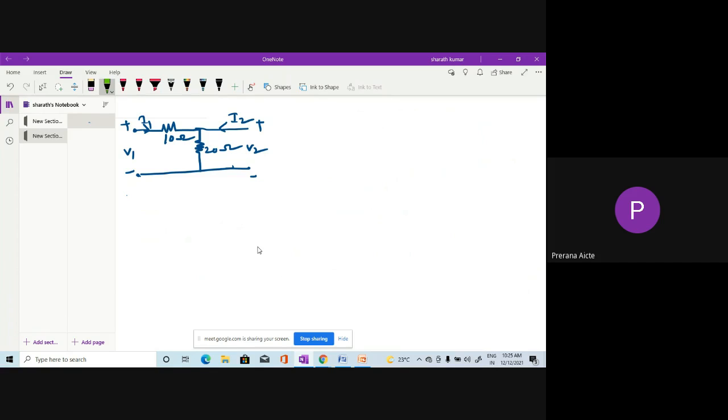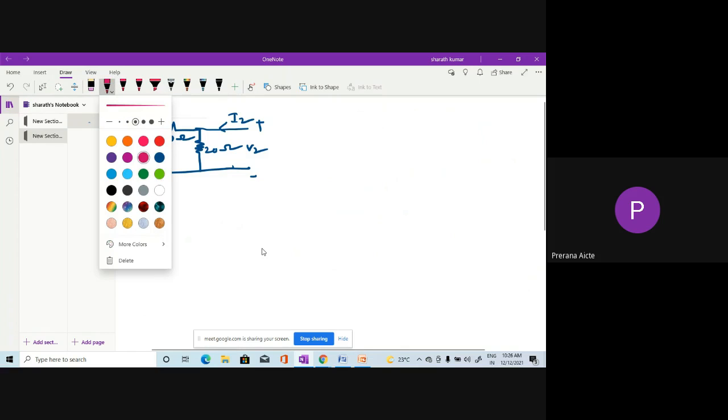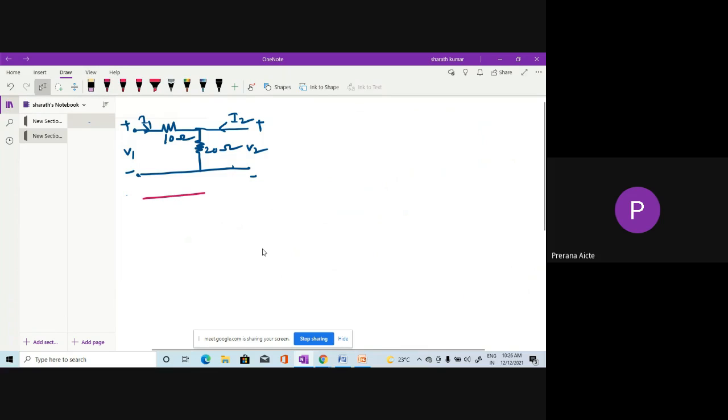If you open circuit, then the values in series with this open circuit are eliminated. Your 10 ohm resistor is in series to your port 1, so it is not going to be considered, because there is no current flowing in the 10 ohm resistor. It's a negligible value.